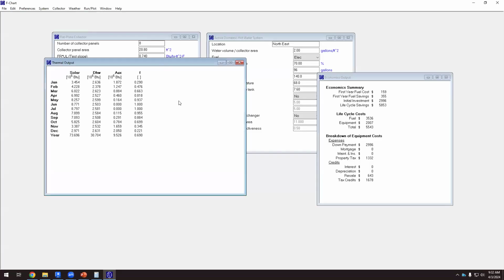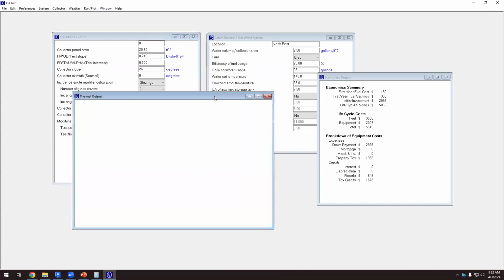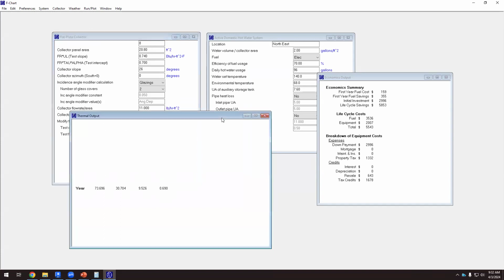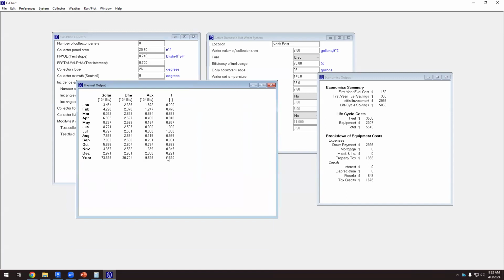It might be different. So with 5 solar collectors, I had like 0.5% of the yearly domestic hot water. I tend to think that 70 is a good number. So with 8 solar collectors, we have 70% of the yearly. And we have in June and July, we cover 100% of the energy we need. I told you that having one, it's great, but if we have one in many months, we might have problems with the overheating.